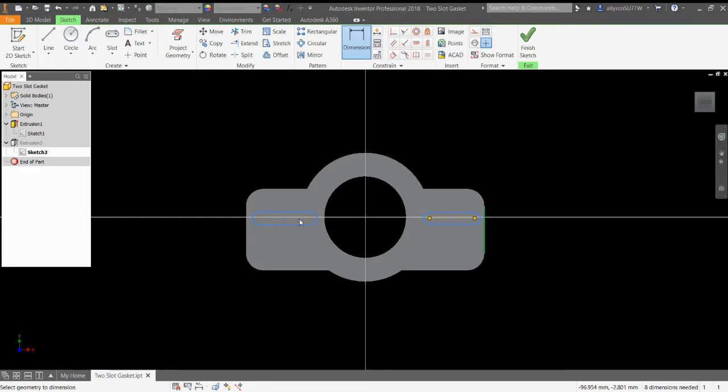And again, when you look at your drawing, it says that it's twice. So I'm going to put a 50 millimeter dimension on here. Then I know from the center of the slot to this line here, that should be 25 millimeters. Okay, so I have that.